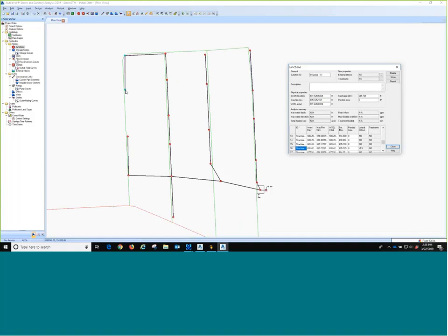What I can do at this point is, if I select a junction, I'll right click and go to Copy Properties. Copy Properties will actually copy everything that I have, like external inflows, if I had treatments, anything that's in these submenus, and then I can paste them to another junction. So I'll just select this, right click, go to Paste, do the same thing over here, right click. I can also just press A in this case. So right click A, right click A, right click A, etc.